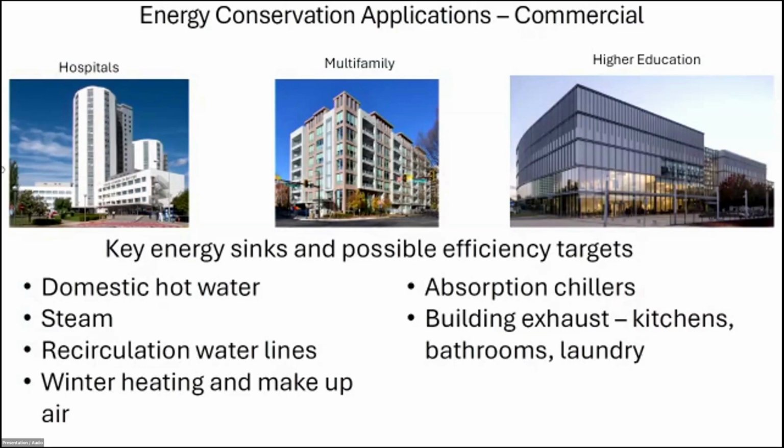But usually what happens is a higher education facility builds a dorm room. They want to be able to cool it, so they want to put in a 500-ton air-cooled chiller. They contact their electric utility and ask, how much capacity do I have left? And they say, none. You cannot put that in. So that drives them to their gas utility, and they ask them, how much capacity do I have? And they say, you have enough. You can put in a dedicated heating system, and you can use that to drive your absorption chiller to be able to provide a cooling cycle for your new building.